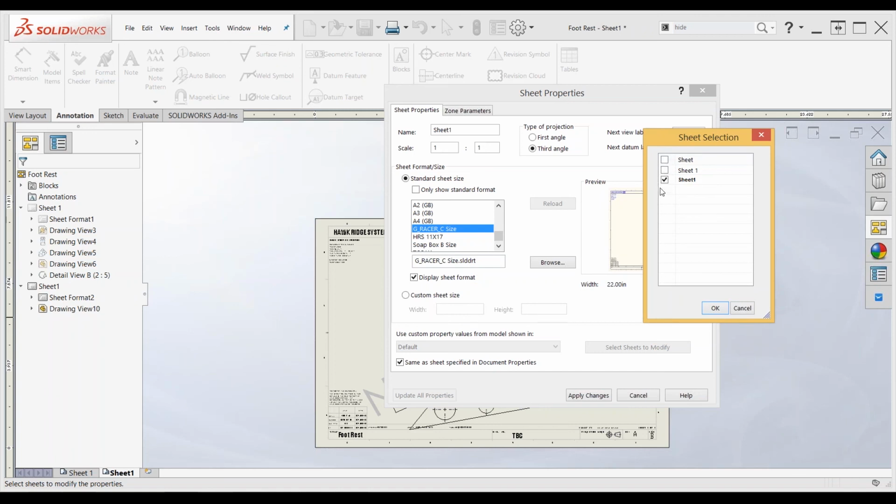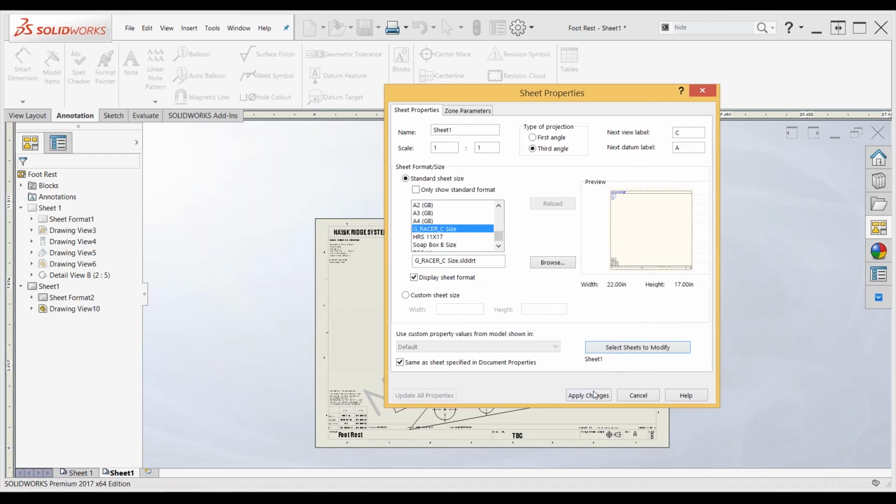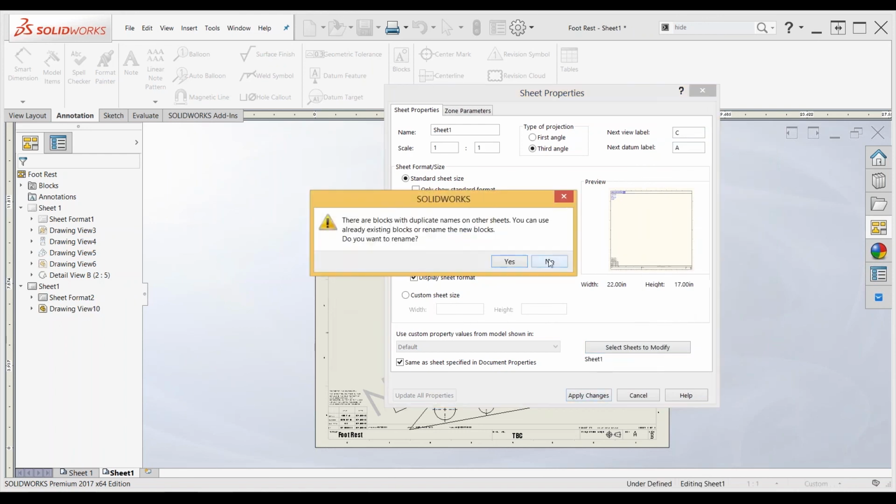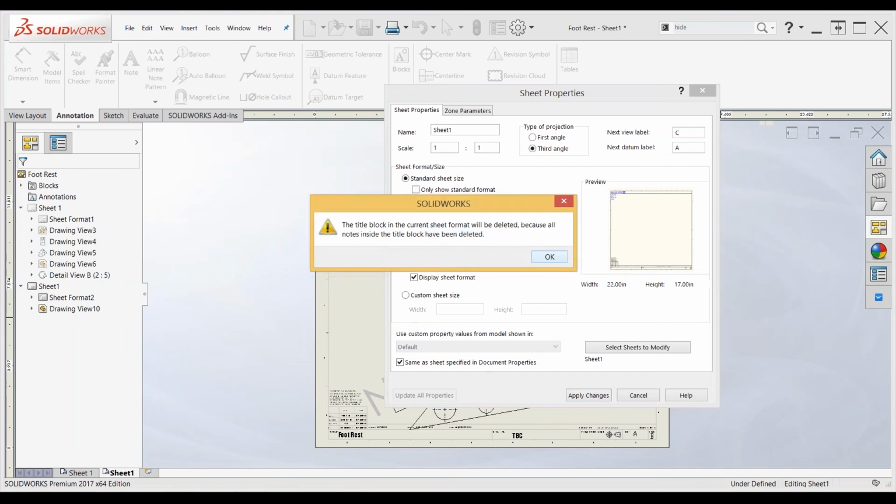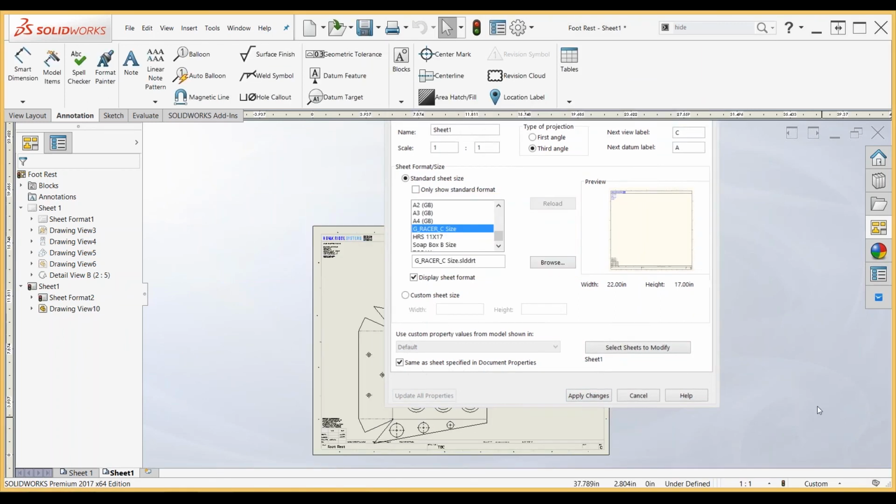0.15 millimeters is all the radius of the cutting tool I'm using is. So you can see it's a really tiny difference, but for high precision parts, your part will come out smaller if you don't actually do this. So that's what I want to do. I've offset my part a little bigger,